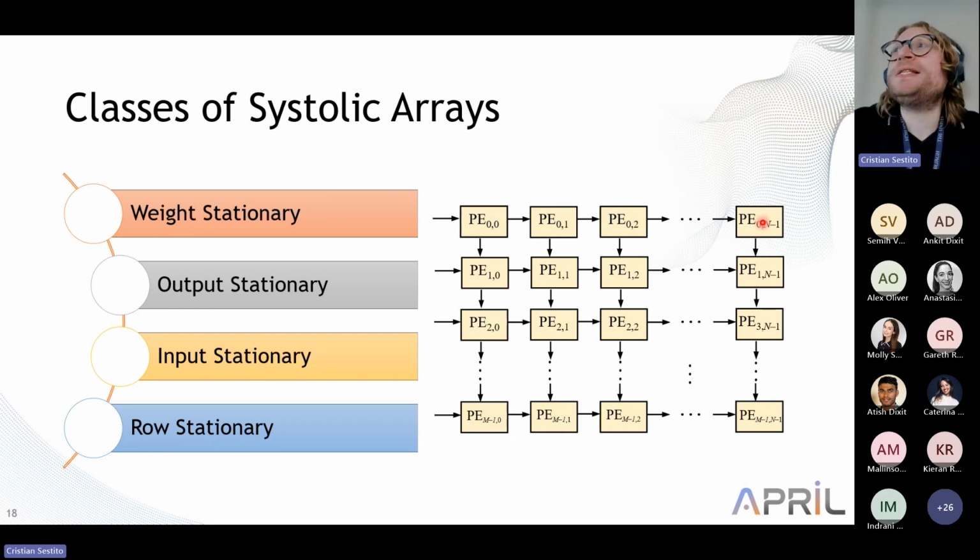If you remember from the slides in which I was showing how a kernel scanned the image, we said the weights are shared for the entire feature map. So we may think that the set of weights is fixed at the processing element level, and they stay fixed until we process the entire feature map. In this way, we are completely cutting the redundant memory accesses to the external memory to continuously grab the weights.